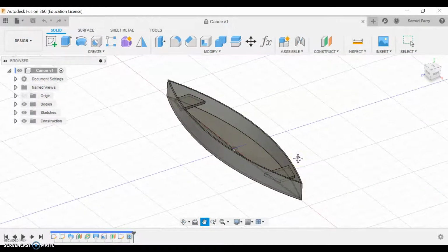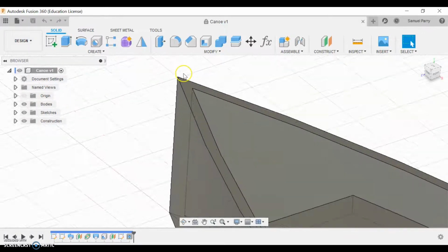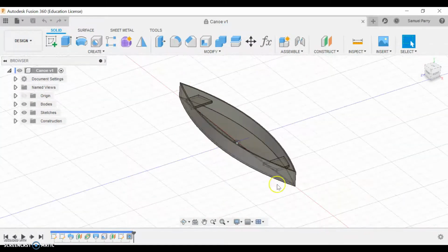and using the shift button. So I'm in pan mode now. I'm just going to press the escape key on my keyboard to go kind of neutral with that. Now with your mouse, you obviously have a left button click, a right button click, and a roller in the middle. Now the roller can act as a roller, but also as a button. Now the first thing to get used to doing is using your mouse cursor and the roller to roll in, to zoom in on parts of your drawing.